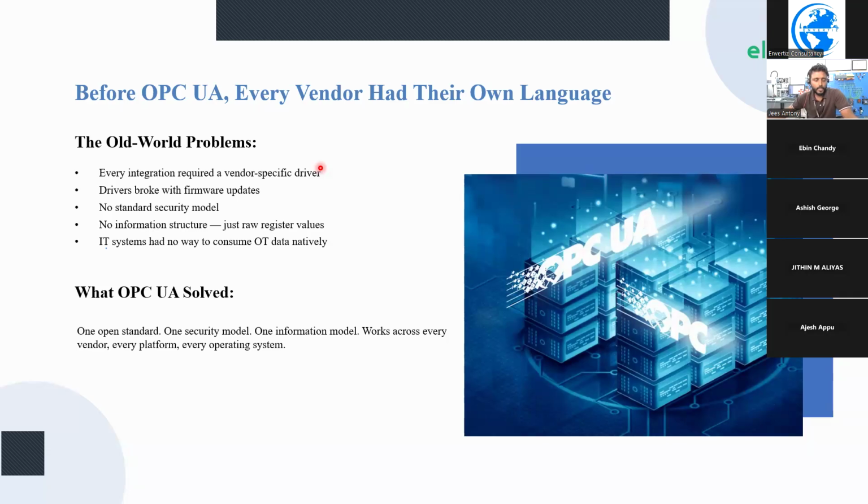To solve that in industry, we have introduced OPC UA. With OPC UA, a single standard can communicate with every vendor's manufactured devices. Since it is a very standardized and very modern protocol, it offers security and scalability, like plant-level name servers that we can keep with OPC UA.